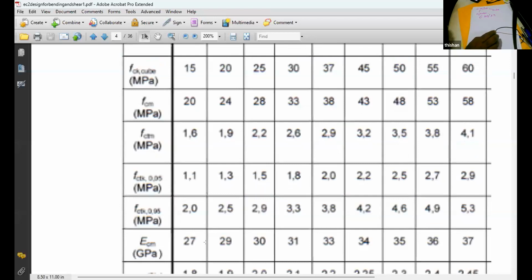But again, the most important other parameter is the elastic modulus. You can see the lowest quality concrete has only about 25, 26, 27, whereas high strength concrete, not extremely strong concrete, has something like 37, whereas extremely strong concrete like 105 megapascal would have about 42.